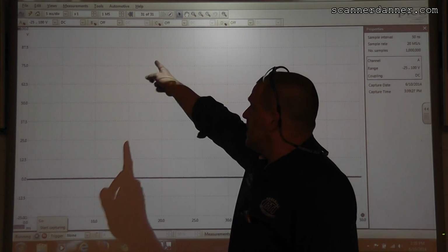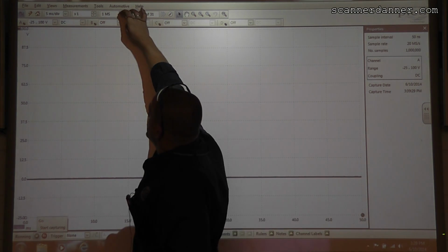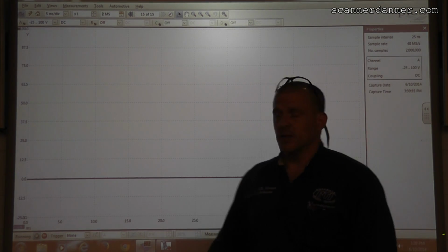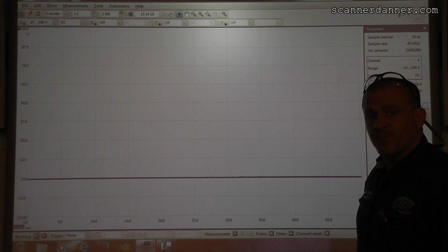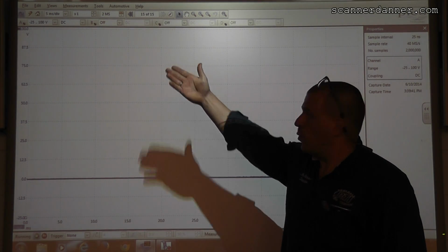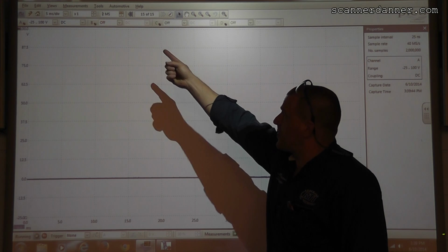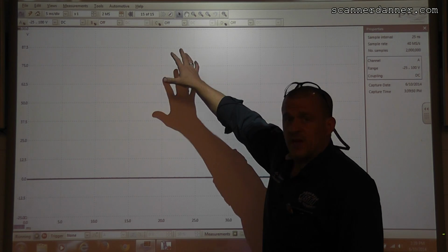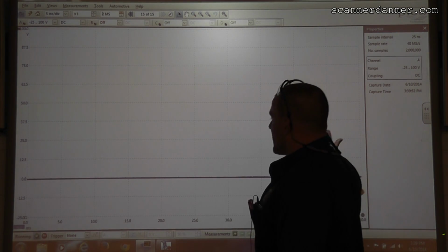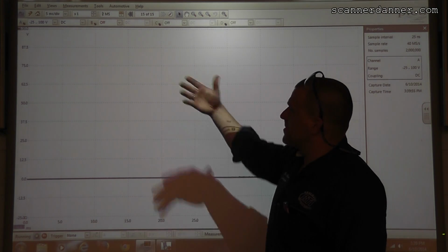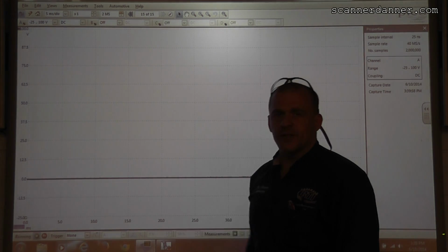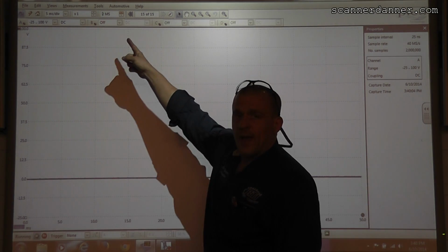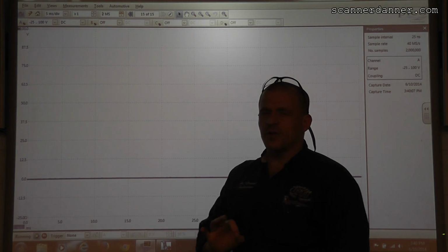Watch what happens when I double this sample rate. So if I go to 2 mega samples, that would be 2 million samples on this screen. Watch the waveform buffer. We only went to 15 this time. Why is that? Well, do your math, 2 million per screen. I have 15 frames times 2, that's 30 million. And then again, the last frame we're looking at, I'm sampling it 2 million times. There's your 32 million. So right away we can see that changing the sample rate can affect this waveform buffer. 32 million is the maximum.